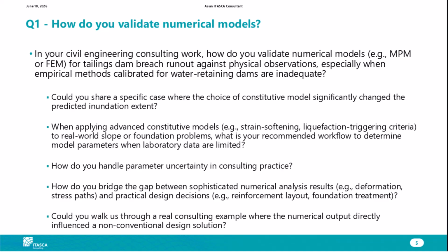Either you have, for example, in FLAC3D, there was the remeshing tool that would allow you to follow the progression of the initial geometry toward a final configuration. And so you may have been able to develop some sort of information about the runout. In 3D, there was nothing. Or you would need to adopt a DEM. The problem with the DEM is that it's much more intensive in terms of computational effort, much more demanding, and so it has been rarely used.